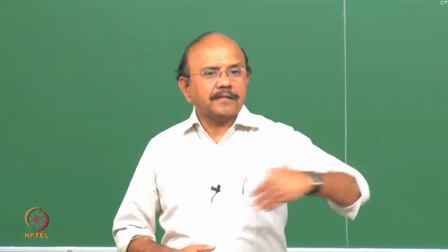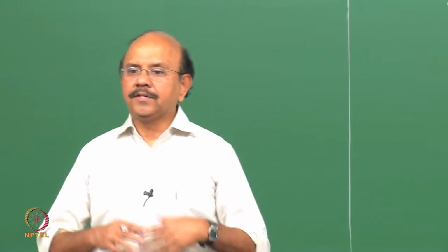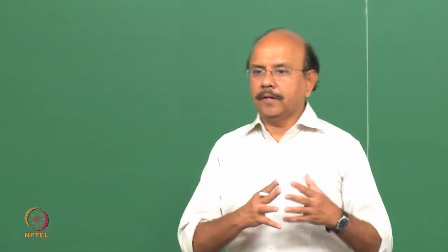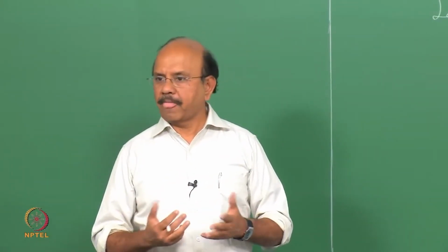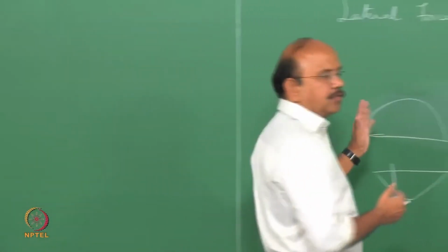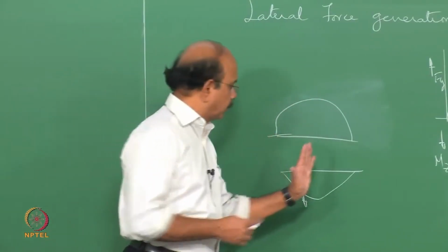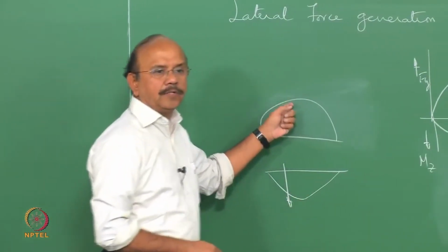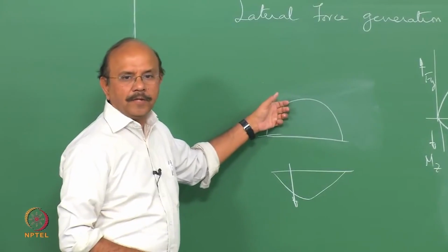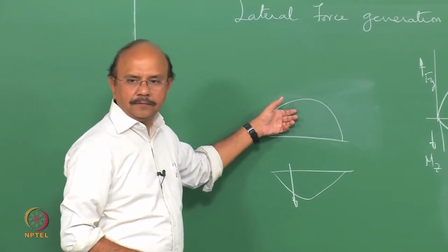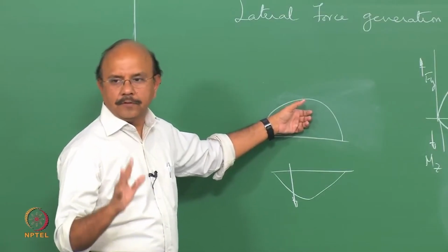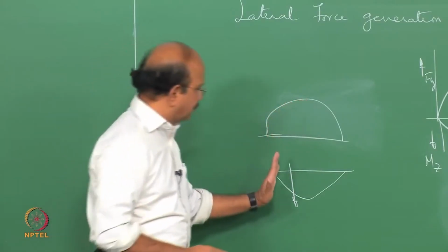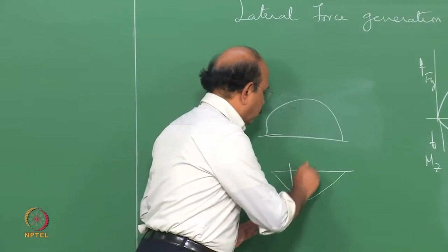Now, imagine that slowly the bristles are going to slip. When it slips, what happens? It reaches a maximum value which is mu into Qz, right? So all of them are going to assume the value of mu Qz, and this being almost symmetric, this one is now going to move towards the center.